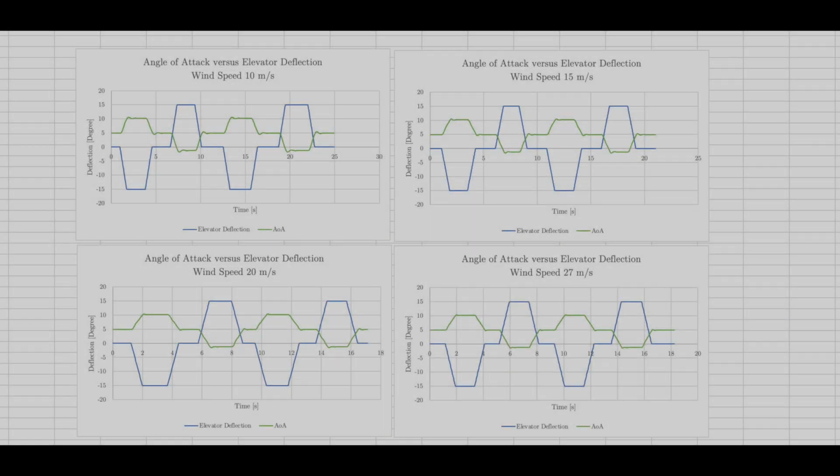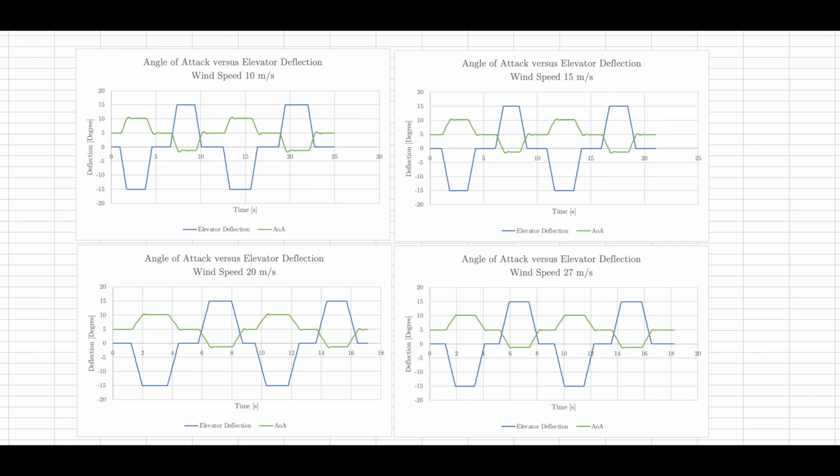These charts show the impact that increased wind speed had on the aircraft's longitudinal stability. As seen, in reaction to a high deflection, the angle of attack amplitude and the time to decay both reduced with rising wind speed. These plots verify that adjusting the elevator in a particular direction will cause the aircraft's angle of attack to react appropriately.